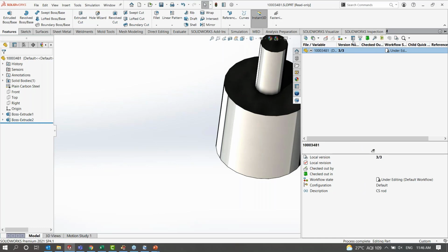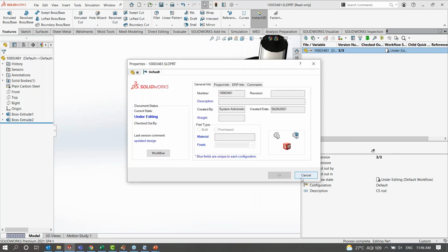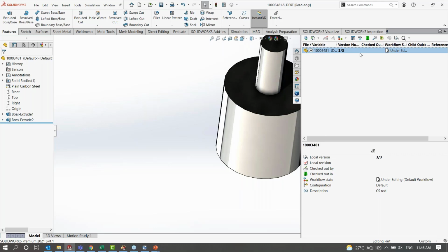Then also the data card can be modified from here itself. Later on, we can even see if it is linked to anything in references, and we can add that. We can just see where it is being used. Also, there is the search functionality right from here. So designers can directly come to SolidWorks, go to the PDM add-in, and start searching for the file that they want from the search criteria here itself.